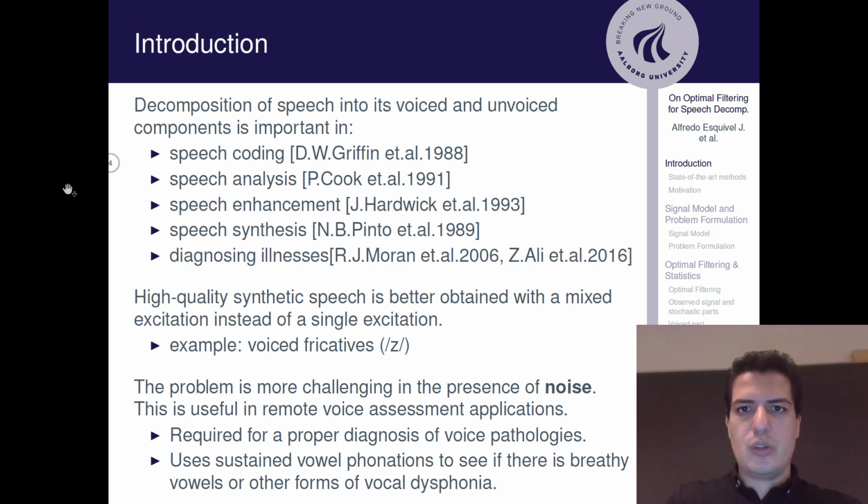The decomposition of speech into its voice and non-voice components is important in many applications, such as speech coding, speech analysis, speech enhancement, synthesis, and of course for diagnosing illnesses. For example, in the case of speech synthesis, better quality speech can be obtained with a mixed excitation instead of a single excitation, as in the example of voiced fricatives such as the Z consonant, which is actually better produced if excitation for the voiced part and the unvoiced part is considered, giving more natural sounding speech in that case.